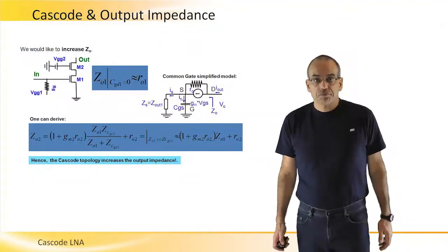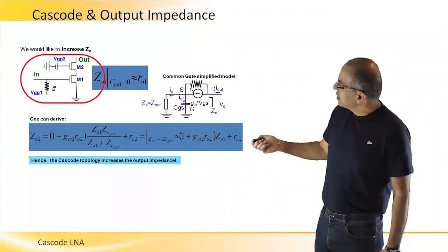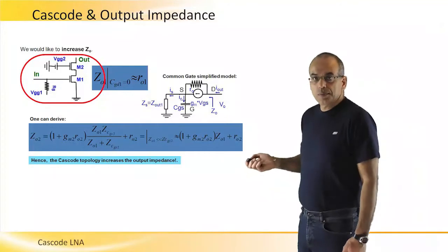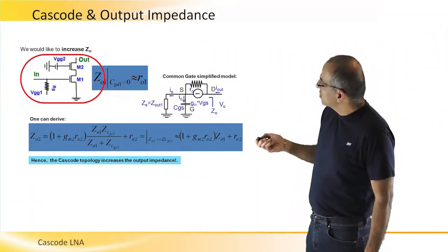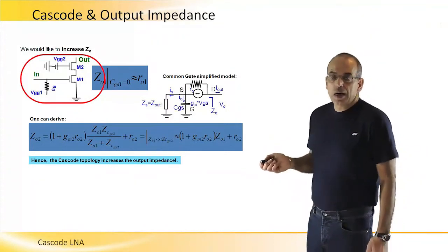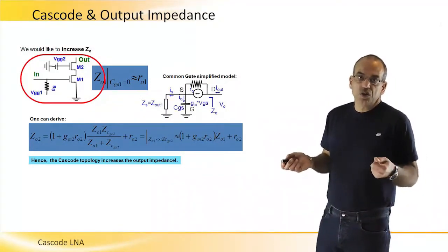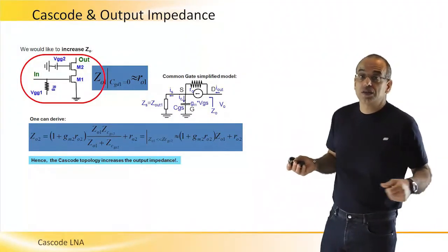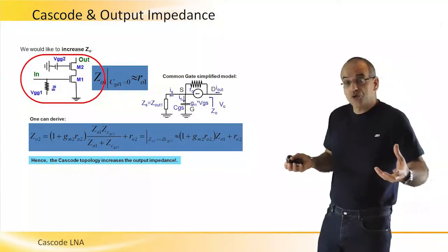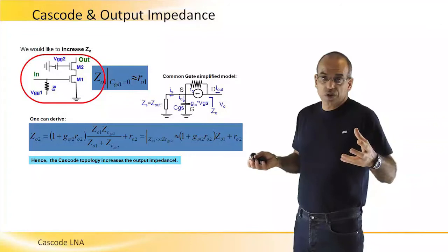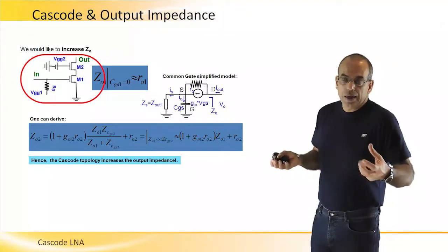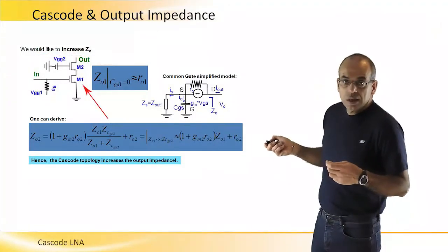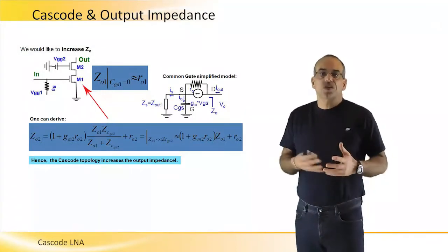So basically here is the Cascode topology, and what we know is the output impedance of transistor 1, where we assume that CGD1 equals 0, which is not true, but it just simplifies our analysis, or it will be more true at low frequencies where the capacitance has very high impedance anyway. So we just assume that M1 has an output resistance of Rout1, which is the RDS of this transistor.